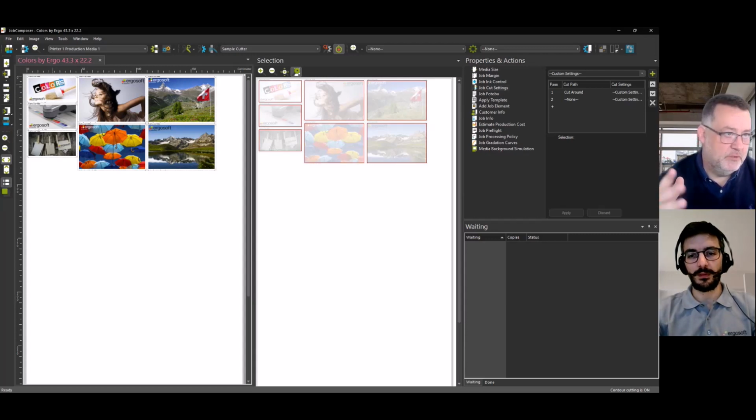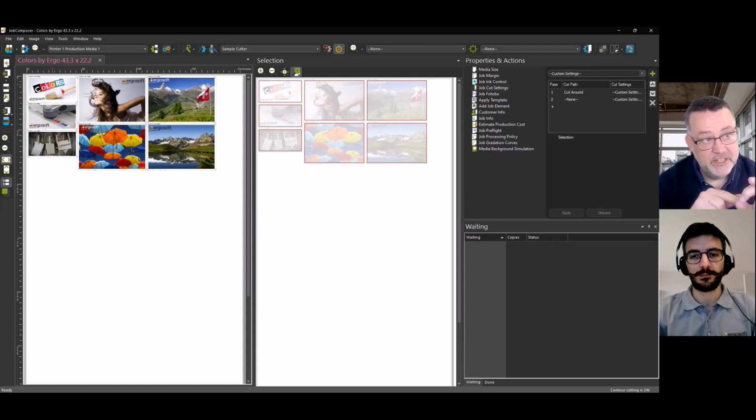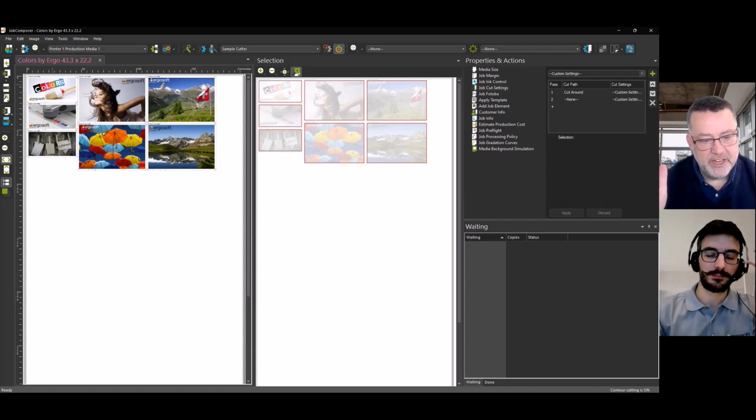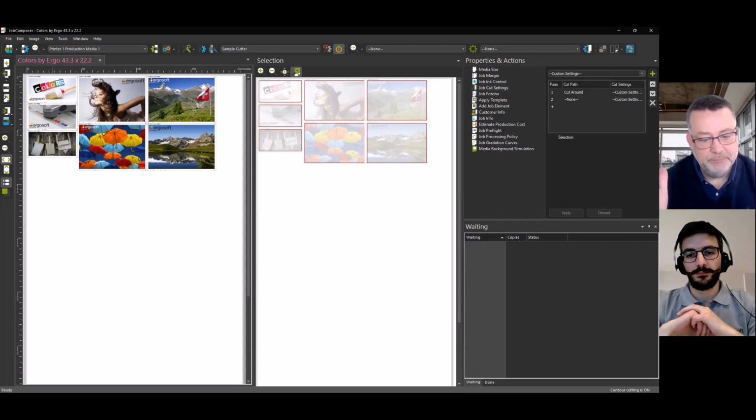That makes it basically easier for all the picking, packing, posting for them. So they get the image file, it arrives, think of it as a circle maybe. It's got a cut path around it. They define that as a kiss cut because they don't want it to go all the way through, so they can peel the sticker. And then they nest those in Illustrator and they send them in 16s or 32s sections, make a canvas again, send that to the RIP, and the RIP prints the files.